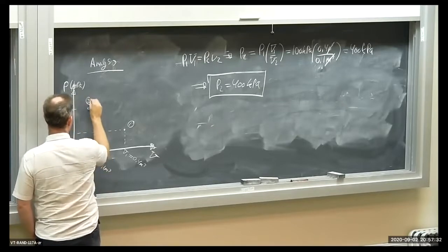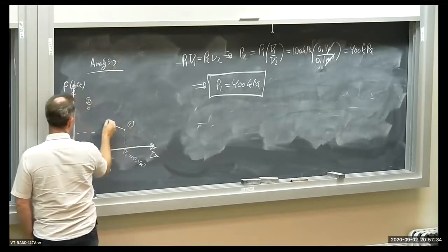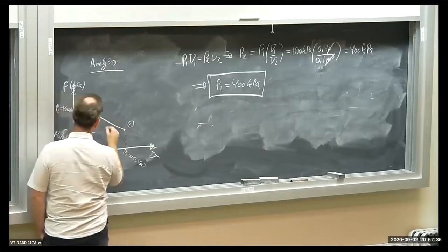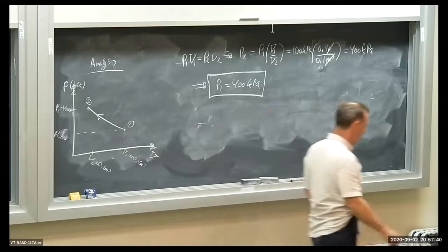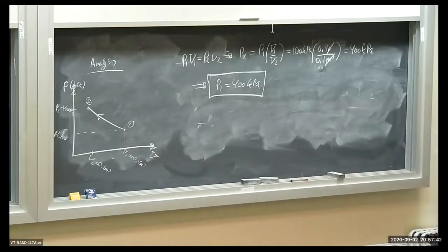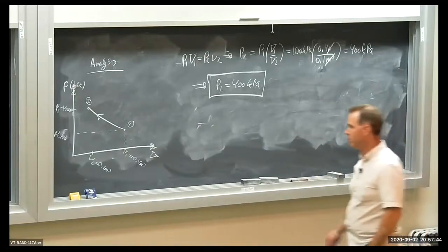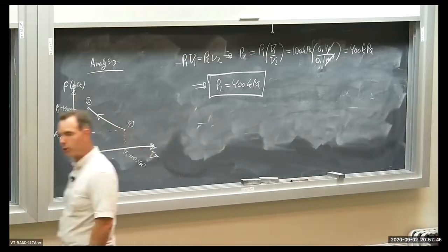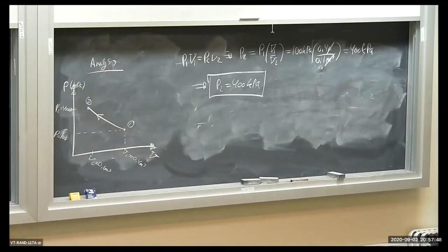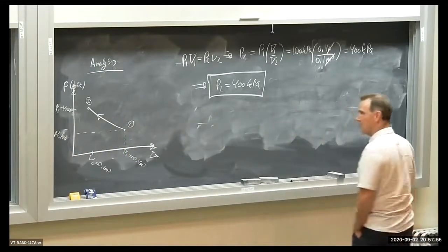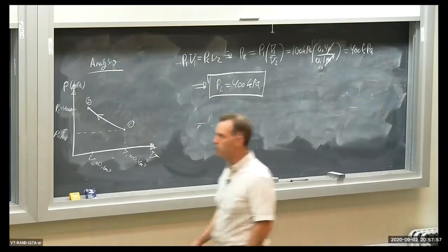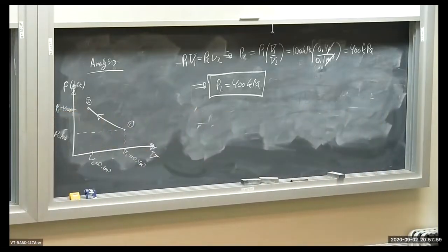So this is state 2. The isothermal compression process looks like that on the PV diagram, up and to the left. It's not a straight line, it'll have a curve to it. So don't make it quite straight. Have a little arc to it. Convex, a bit of convexity to it. Okay, so that's P2.